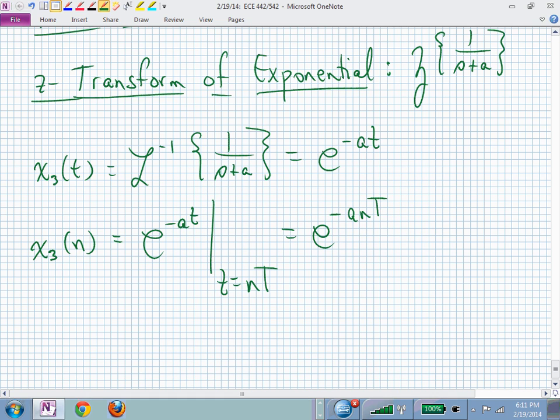But we can maybe z-transform this, or we can now say, what's the piece of this e to the minus a n T that's actually varying? Just little n. All the other pieces are fixed, which means that we can rewrite that, knowing our math behind exponentials, as e to the minus aT to the n. But then we could say, you know what, that's just some number, r.